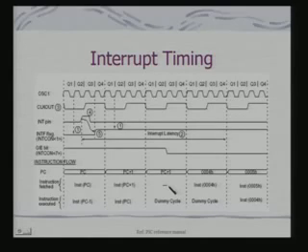in that cycle. And in this cycle, what you do is, basically the instruction that you have actually fetched is not being used. So, instruction fetch has a blank over there, and the PC is effectively set to the vector address. Now, you fetch the instruction here, and here also execution-wise it's still a dummy cycle because you have not got the instruction to execute.